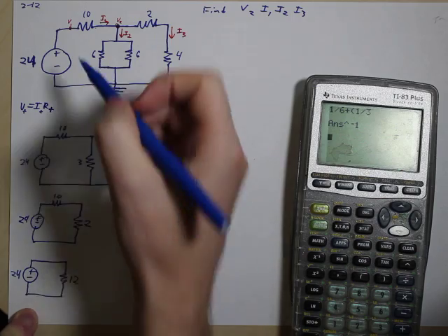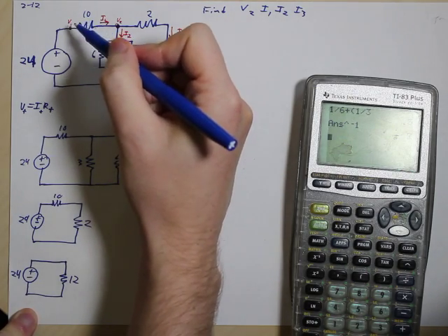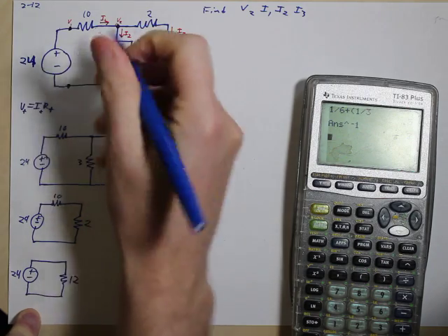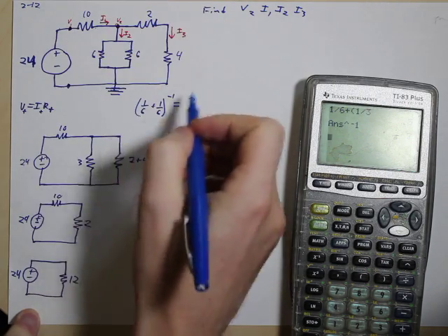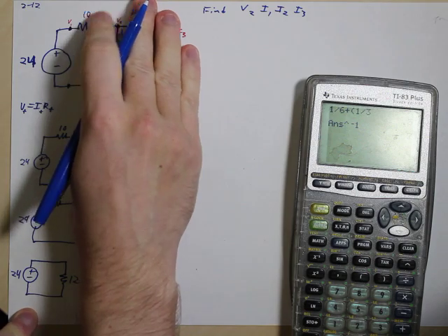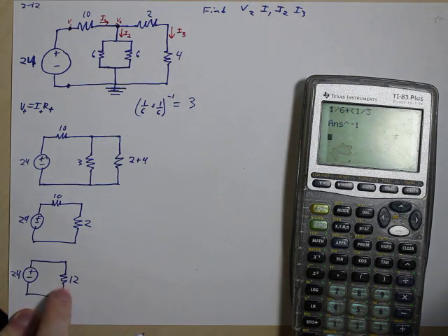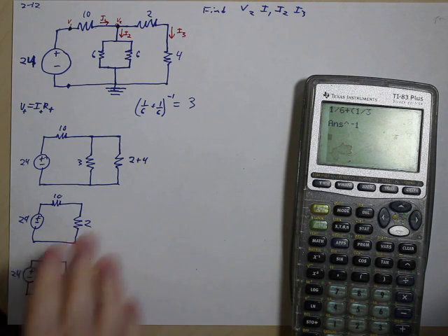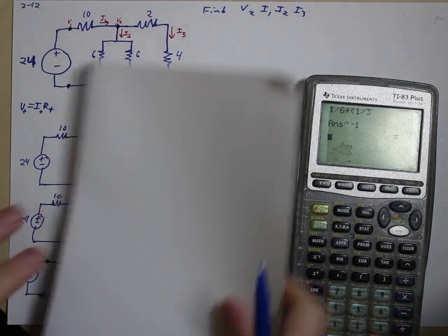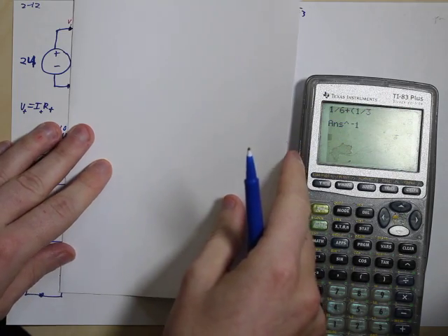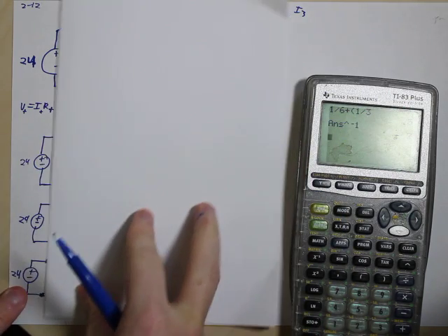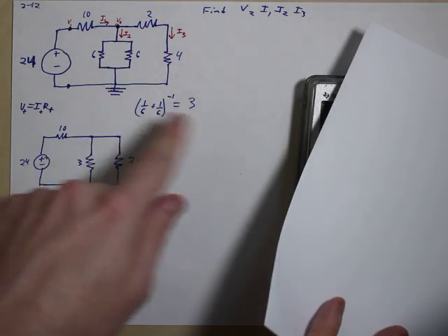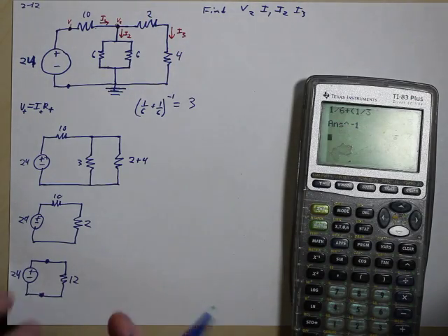So if you look, if I just took 2 points up here from here, let's just say I made that as the point V1 here, and whatever happens over in this half, this whole box is being simplified into this one resistor, because essentially this is the same test point. So if we hide that half and we're saying what's happening over there, it's the same as saying this half right here equals that whole chunk. So we've simplified it.